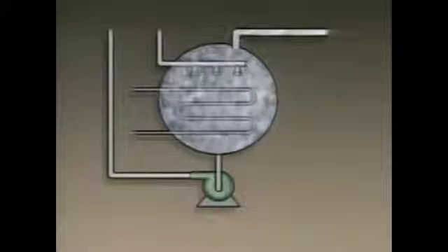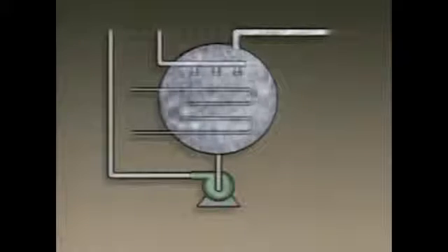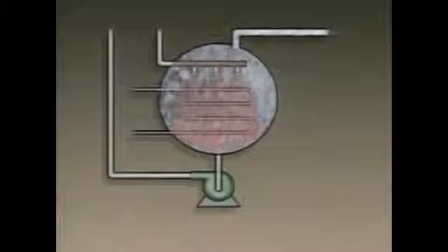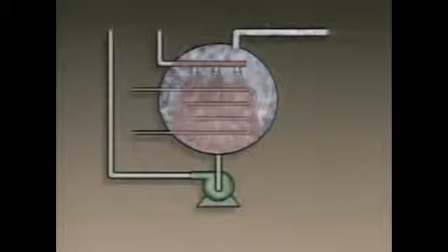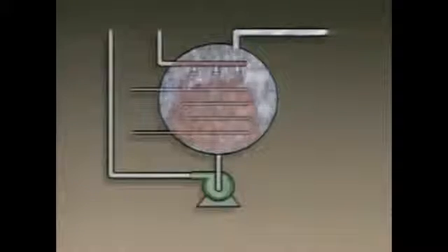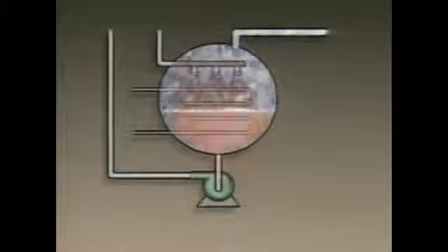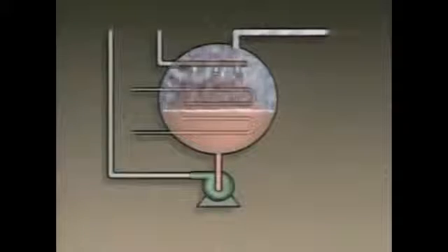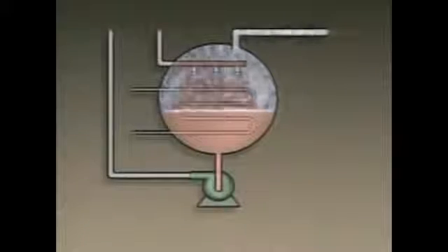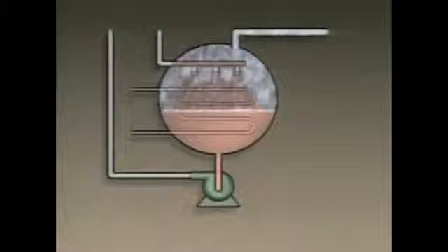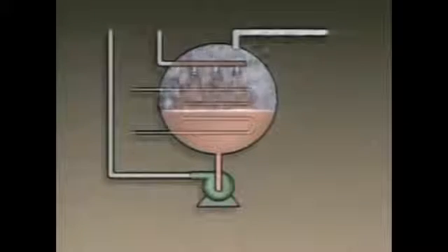The refrigerant vapor from the evaporator flows into the absorber section, where a relatively hot lithium bromide solution is sprayed into the vapor. The lithium bromide absorbs the vapor, and a mixture of absorbent and refrigerant is formed. When the lithium bromide absorbs the vapor, the volume of the vapor is greatly reduced, which causes the low pressure.